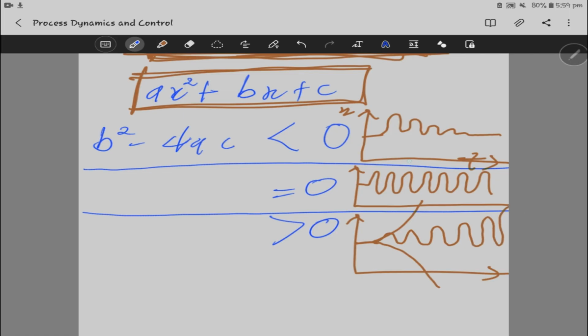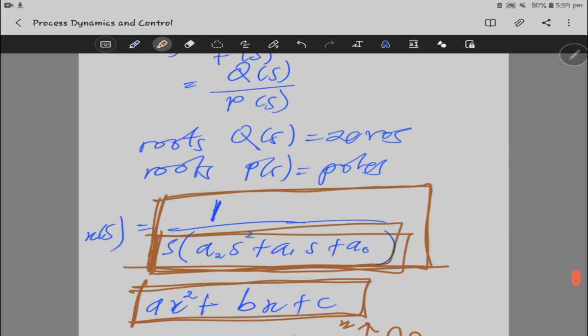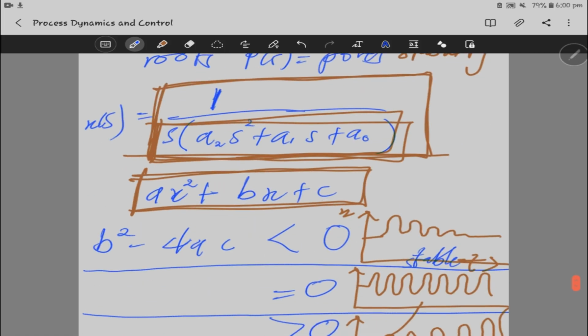So these poles and the zeros tell us a lot about the stability. So this is stable, and they even go on to tell which configuration to use for a particular system. And this here is unstable. They give a lot of information about the system. So clearly the poles give the system stability, and some other information, but here you're looking at just this field. And then the zeros can tell us the shape of the response of the output. So these are some of the information that these two can give us.